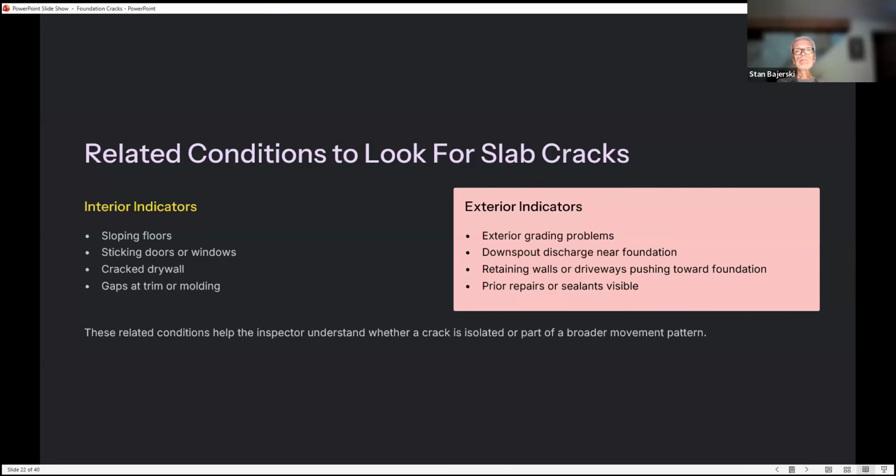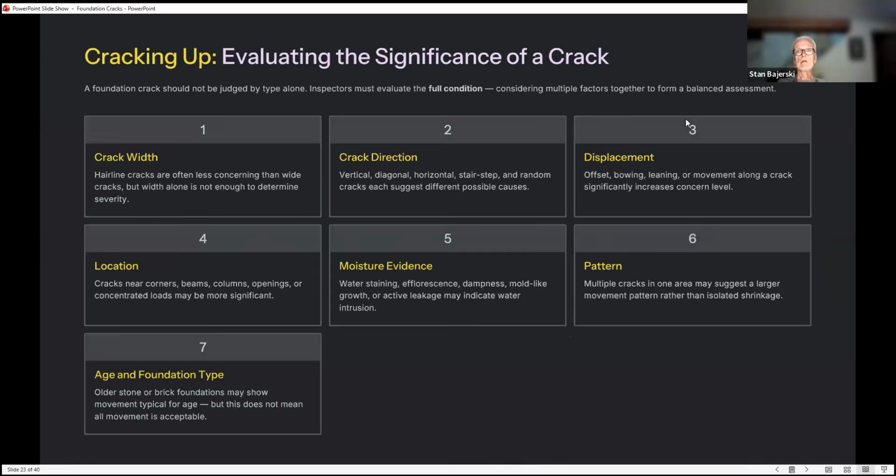You know, the water issue is a big deal in a house in many, many different ways. And a lot of times correcting drainage around the house is going to fix a lot of other issues. You know, even gutters that are dumping water around the foundation, all that's got to be taken care of when you suspect a foundation or slab problem.